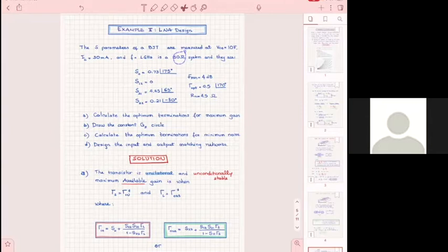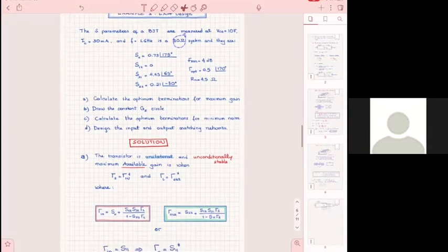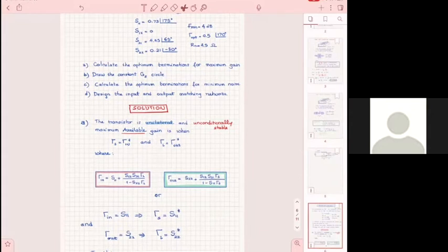And that means that the gain of every section, the input matching network is a section in the amplifier, the transistor is a section, the output matching network is a section. The input section and the output section act independently. That's what it means. So practically there's no feedback, because if there is feedback, then they see each other. Okay. Now, what happens when a transistor is unilateral? What happens in terms of stability?